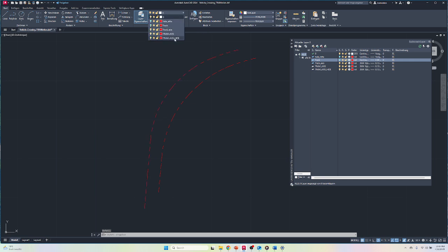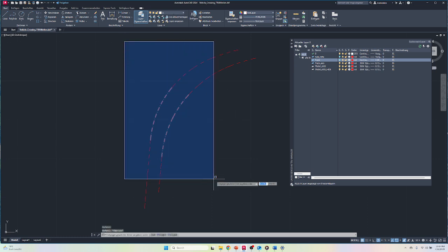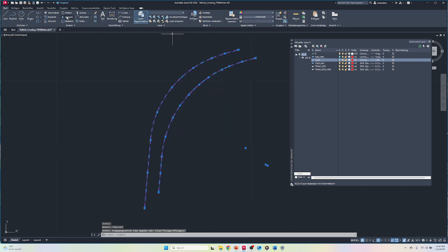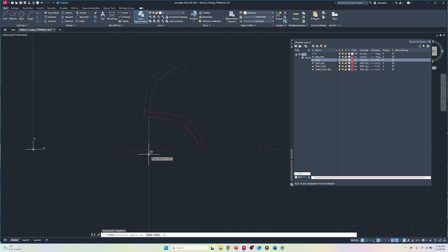Before saving the data, the track sections must be properly aligned to ensure correct processing. The polyline under investigation should be horizontal and ideally begin at 0. That is, horizontally from left to right. However, this requirement can be handled somewhat flexibly, so the origin doesn't need to be exactly at 0. As a result, the second section stays the same, which guarantees that the relative positioning of both tracks remains intact. After complete preparation, the file is saved in DXF format.